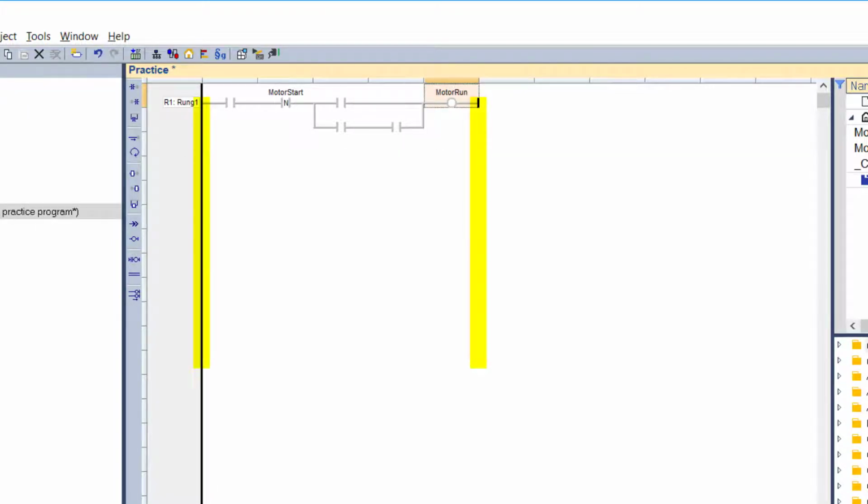Vertical power rails are used in ladder diagram for representing the limits of a rung. The power rail on the left represents the true value and initiates the rung state. The power rail on the right receives connections from the coils, but has no influence on the execution of the program. When programming, you can use the Align Coils icon to line up the right power rail of all your rungs.